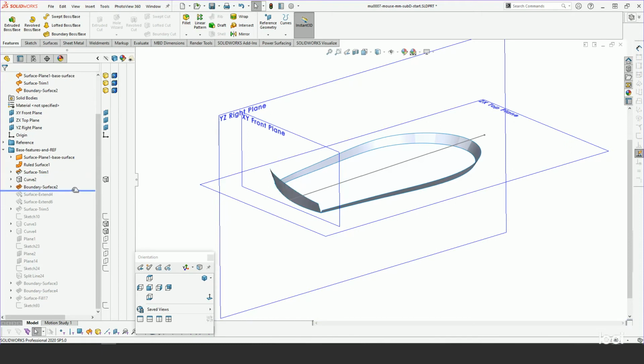On the front of the mouse, there's also a somewhat ruled, it's not actually a ruled surface, but kind of a swept surface for the front. And I'm doing some basic surface modeling to get those surfaces. It would be probably a reference surface because I'll probably end up using the sub-D modeling with a hard edge at the front, but this is an important reference to do that.